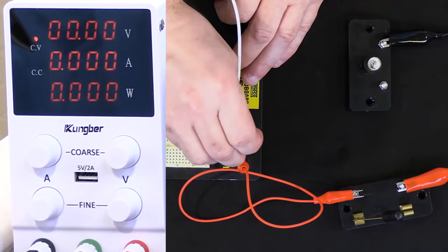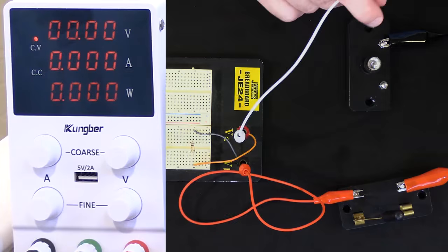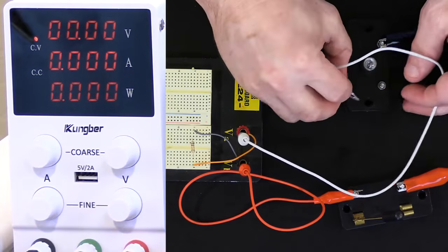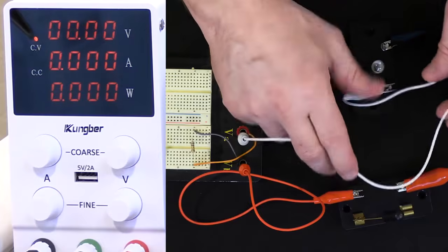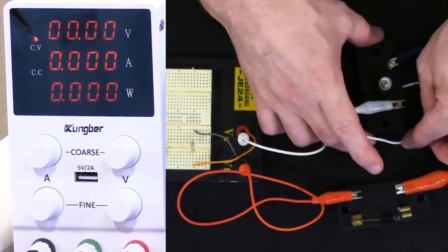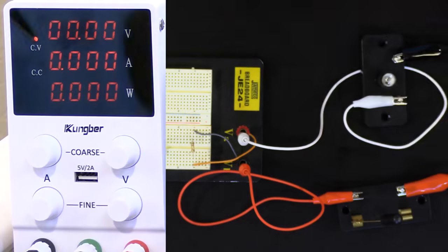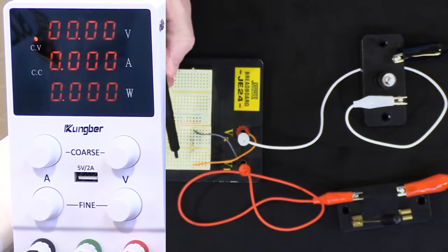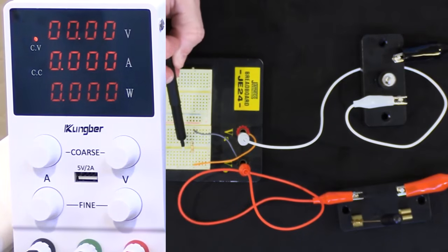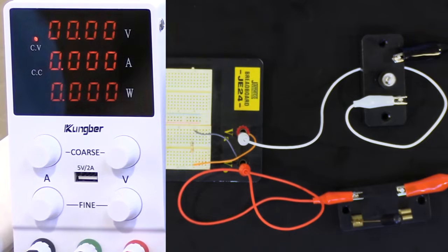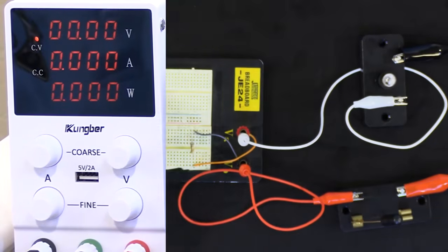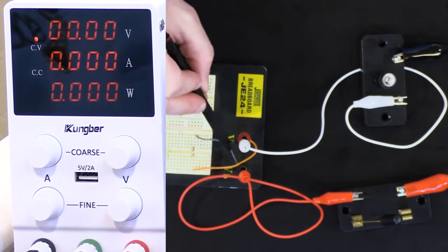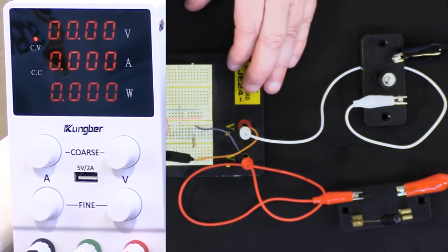And I'm going to show you how this little breadboard device works. We're going to use it a lot because it's very, very easy and helpful to build circuits rapidly. So you're not doing soldering or anything like this. So here we have, if I can get it to stay down here, that's pretty good. The way this breadboard works here is the resistor is plugged into this line here. When you see this line of little holes, this line of holes are all physically connected together underneath. So there's a wire coming from this terminal up here, and there's a wire, you can see the gray one, going and plugged in here, and the resistor is plugged in the same row. So anytime you plug something in any one of these dots, they're all physically connected underneath.